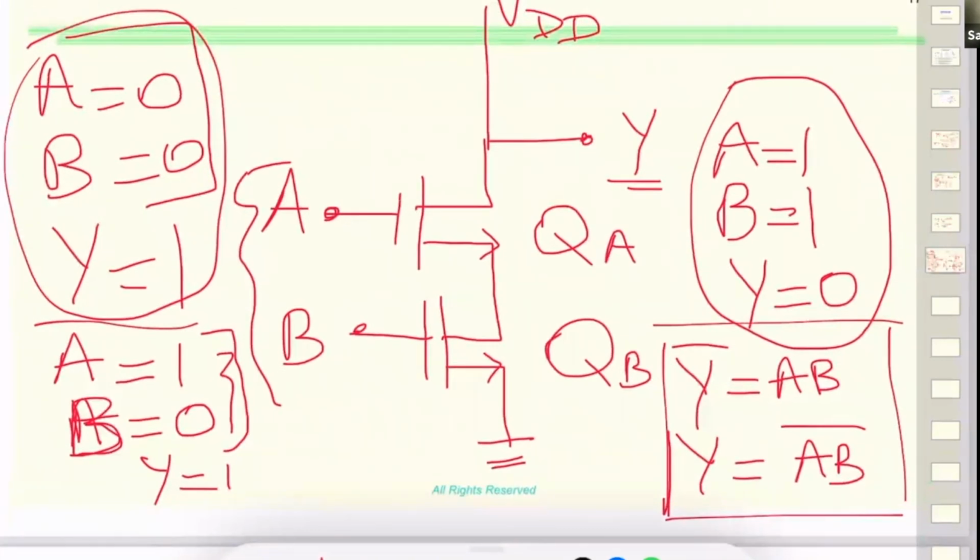Let's stop here because we're going to be implementing more of these. I want you to get some feel of how we translate the behavior of the transistor into digital output. We operate transistors in triode for our logic, because that's where zero means cut off and some voltage is where you are in the triode region.